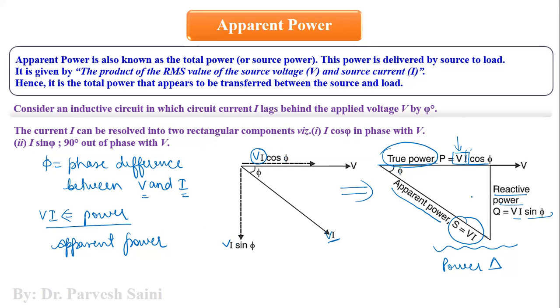Now, what is this reactive power? What is this active power? This is the question now. In our previous lecture, we have seen that in a pure resistor the average power is V into I. In a pure inductor, the average power is 0. In a pure capacitor, the average power is again 0. Now, what does it mean? What do we understand by zero power in the case of an inductor and capacitor? And why do we have power equal to V into I in the case of a resistance? This is another question associated with the concept of power in electrical systems.